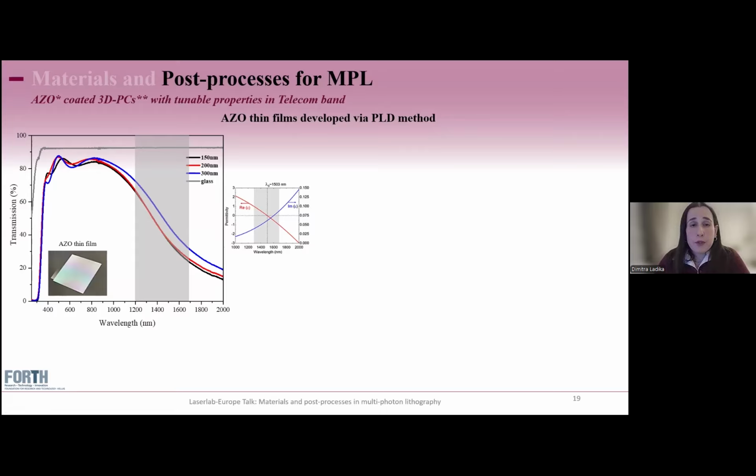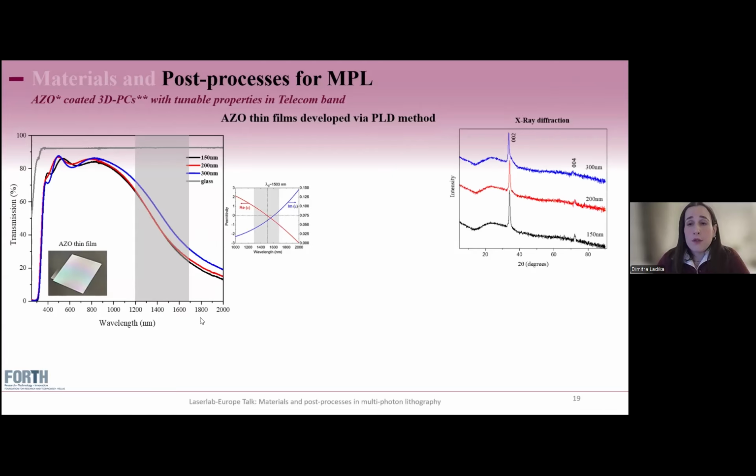Of course, because we're speaking of crystalline materials, we conducted X-ray diffraction measurements, and we saw that we have the hexagonal wurtzite crystal structure of zinc oxide, as we expected, with the c-axis perpendicular to the substrate surface, meaning that we have the polycrystallinity that we want for the films in order to be highly transmissive, as we saw. The valley probably represents the amorphous aluminum.